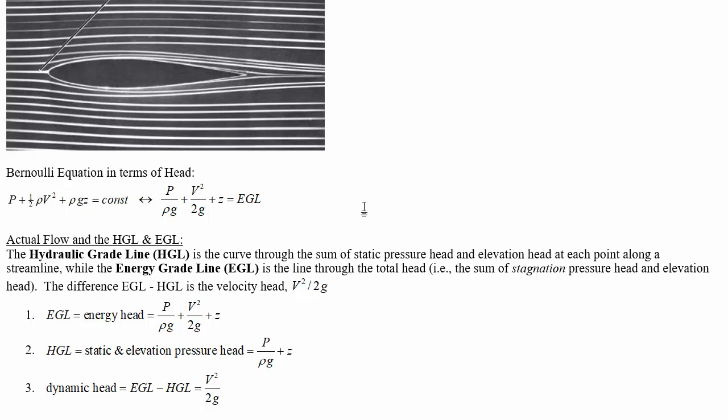Sometimes people like to refer to this just by the depth that it would be at for a given pressure. So you can say, oh, there's a pressure there equal to 10 meters of head, or there's a pressure there of 15 meters of head, meaning that it's the same pressure that you would have for a 15 meter depth increase, 15 meters going down, 10 meters going down. All right, it's not necessarily referring to water, but it would be for whatever fluid you're talking about. Specifically then, this one here is the elevation head.